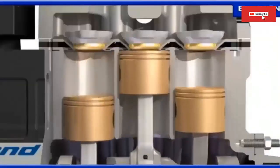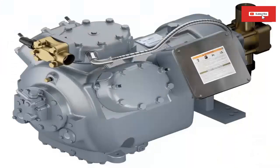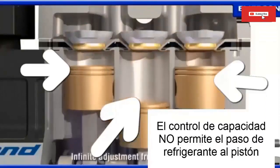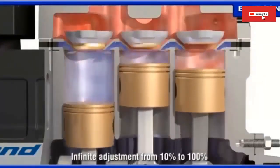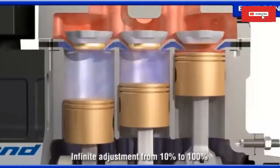Most large reciprocating compressors, above 10 tons, 35 kilowatts, are equipped with cylinder unloaders. 5. The unloaders are used to match the refrigerant flow capacity of the compressor to that required by the application. 6. The regulation is achieved with the progressive deactivation or activation of the passage of refrigerant to the compression chamber of the piston compressor.